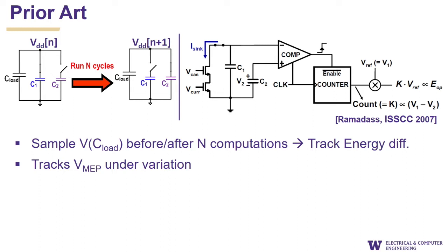given up by this capacitor that was used for storage, right? That's the basic idea. And this is constantly run and operated to make sure that you can run for n cycles with minimum discharge of your capacitor. In other words, you're dissipating your minimum CV square difference in your capacitor. So you're dissipating as little energy as possible in order to run your processor for n cycles.